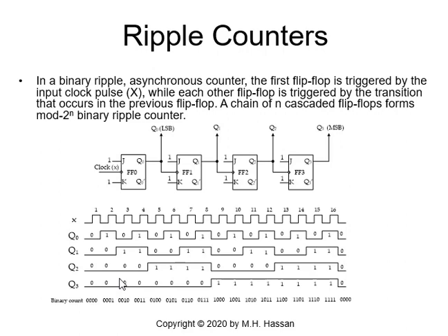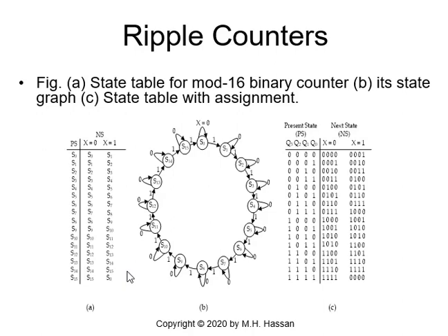So with this in mind, this gives me a ripple up count, not a down count. Now with the ripple up count, we can generate the state table and the state graph. This is how it is shown. If we start with state 0, with the clock pulse we go to state 1. With the next clock pulse, we go to S2. If there is no clock pulse, I remain in the state. I will hold until we have a clock pulse, and so on and so forth.